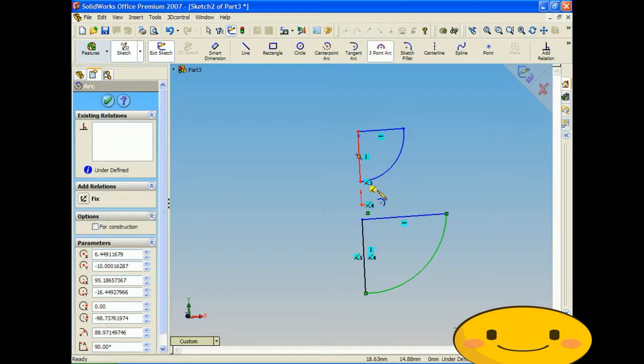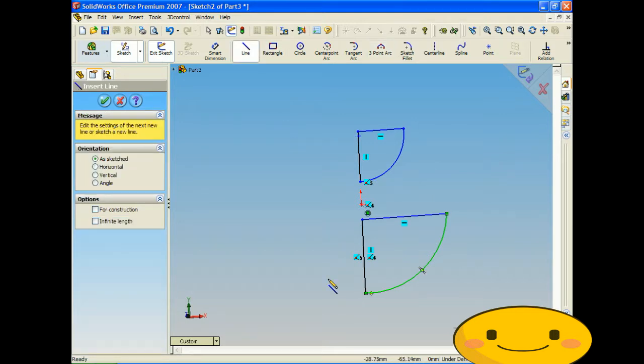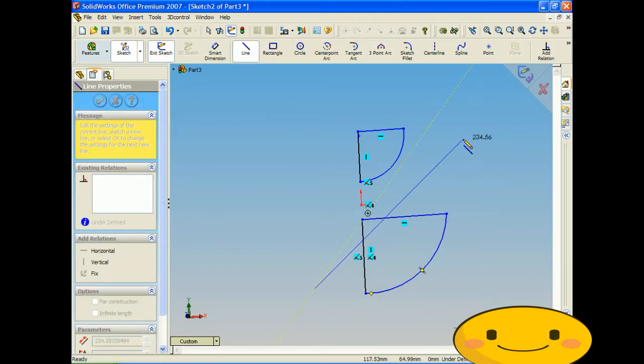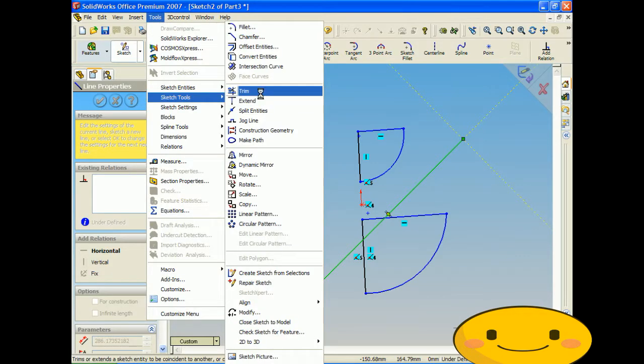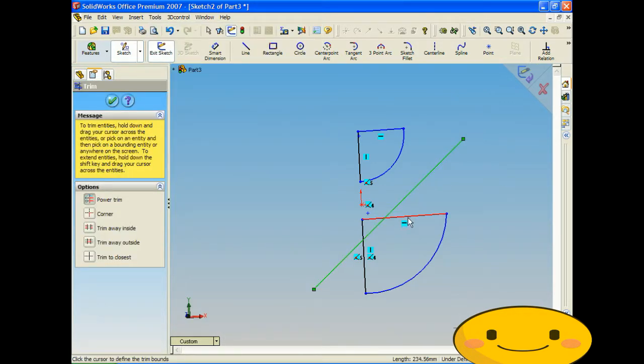But you'll find sometimes if you have a surface that you're sketching on and you have a couple different points, different geometries you're trying to bring together, you're going to have moments where a line runs through like that. And there's no way that you can really dimension it any other way than running it through. So then you'll have to go back into your sketch tools, use the trim, and then click that line, trim it, click that line, and trim it.